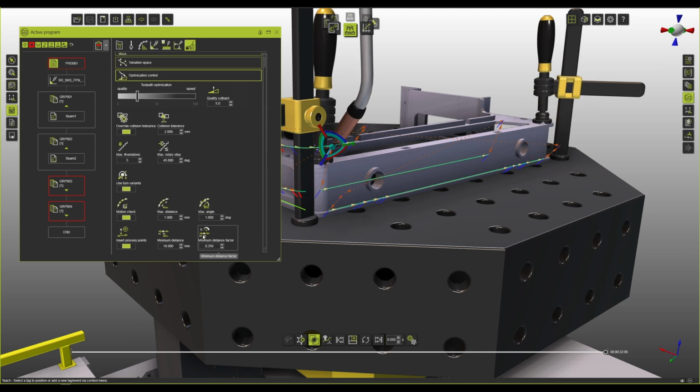And for the inserting process points, it needs at least 10 millimeters. And this is what I was saying, that you need the space to insert these extra points. So if your toolpath is small and you're seeing some sections where it might have a collision in between, just disable the insert process points and have an overall change. You can have this by default. And in the very long paths where you have tiny collisions in between, then you can insert the process